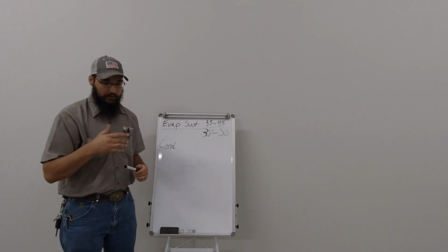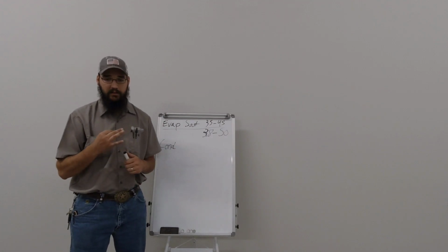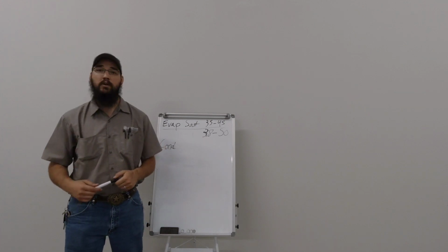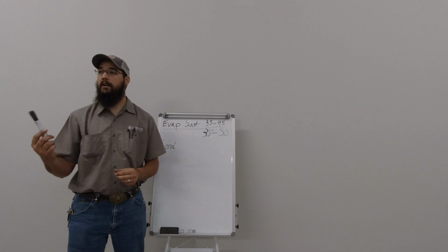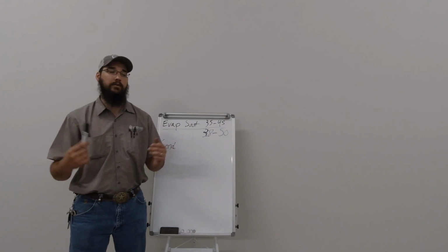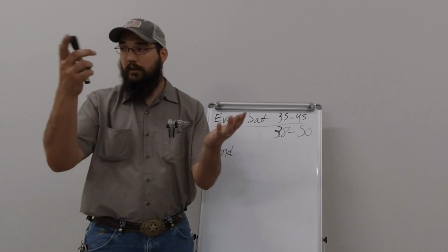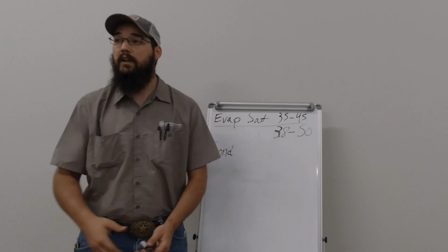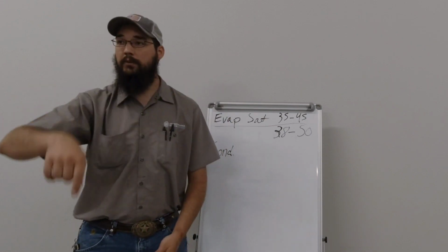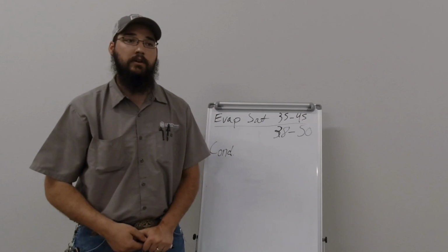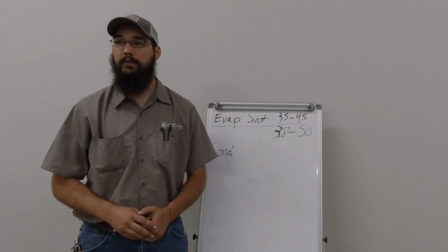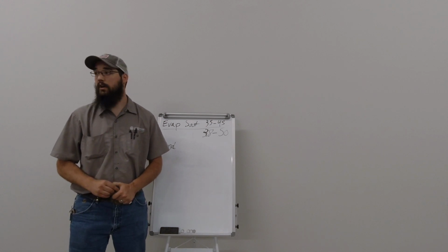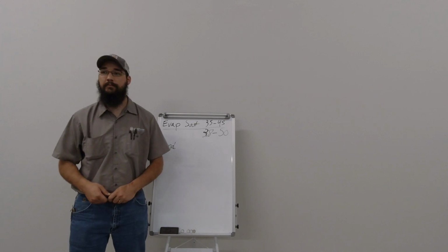There was a property I used to service, had 6 of them. Little package units. Every single time the lawn crew would come by and mow once a month, somebody'd have to go in and wash the coils the day after because all the units would start tripping high head. You show up and it wasn't that much on the coil. And it wasn't a real dirt patch spot. It was just a simple fact that a couple of loops around with a mower in close proximity with the units running was enough to start tripping high heads. You'd walk up, you wouldn't think it would be the case just by looking at the coil visually. As soon as you wash it, everything would be good. They were perfectly fine until they mowed again.